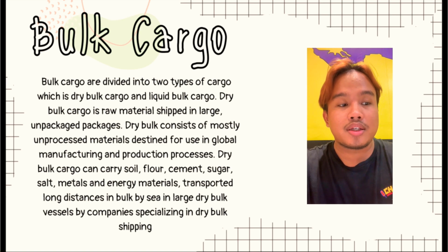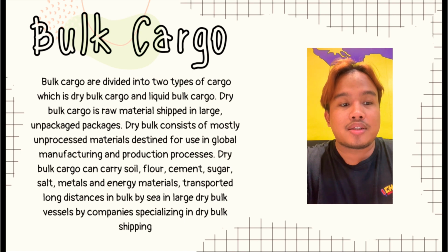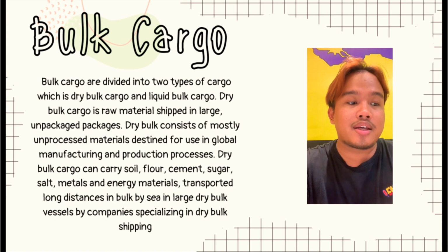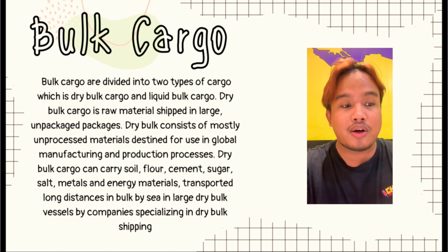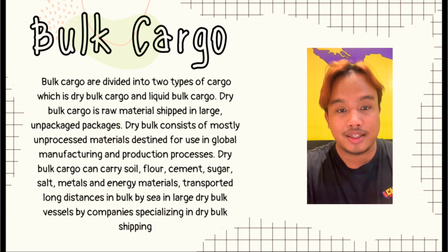During the loading, shipping, and unloading process, daily checks on tank usage, temperature, and inert gas pressure should be carried out and carefully recorded. If the liquid bulk cargo is dangerous, a temporary warning in English is displayed in a specific place where passers-by can easily see it.